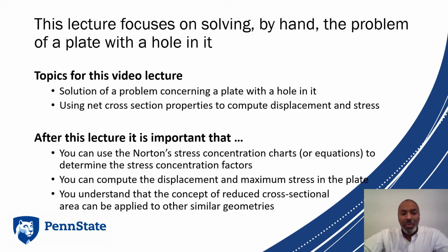After this lecture, it's important that you can use Norton's stress concentration charts. I'll give you one here, and we'll give you some later for a later assignment to determine the stress concentration factors. You can compute the displacement and maximum stresses in the plate using these methods.